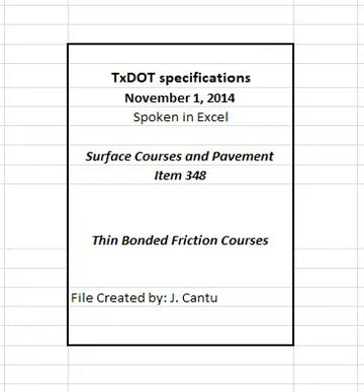2.6 Additives. Use the type and rate of additives specified when shown on the plans. Additives that facilitate mixing, compaction, or improve the quality of the mixture are allowed when approved. Provide the engineer with documentation such as the bill of lading showing the quantity of additives used in the project unless otherwise directed.